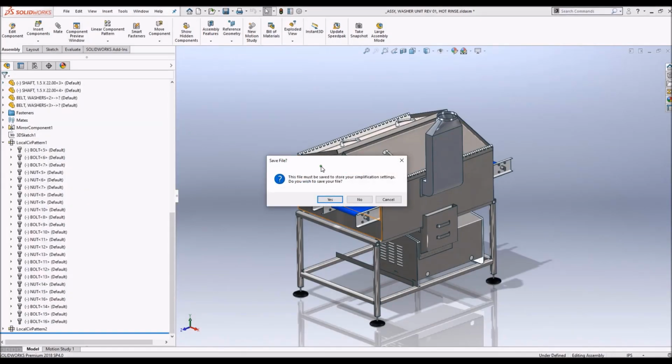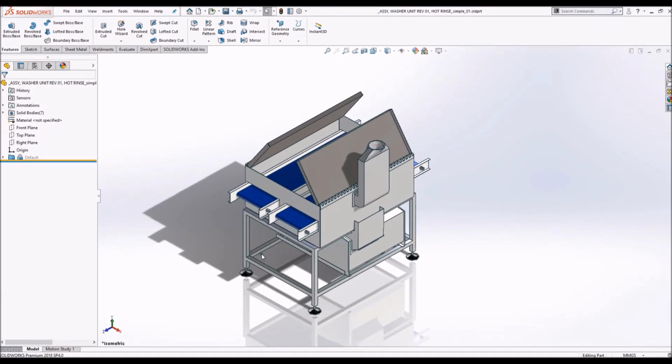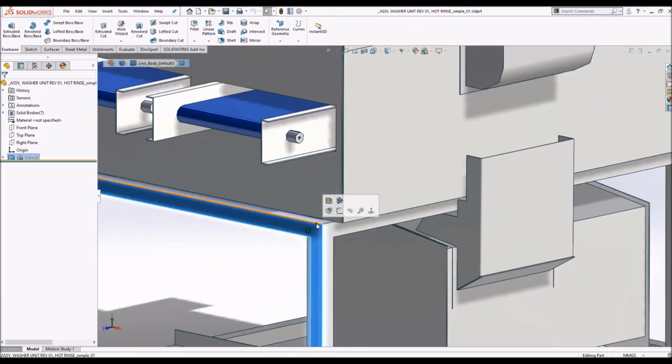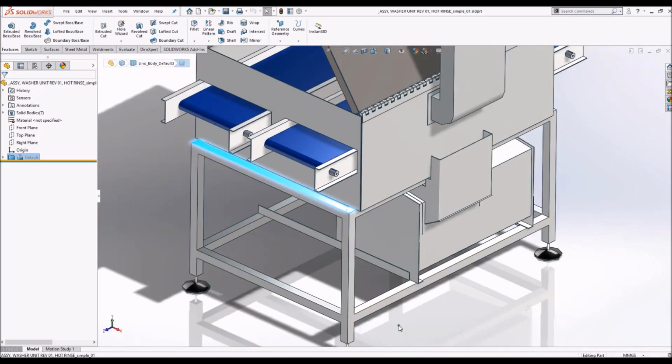When all settings are done, the simplification process can start. We save all settings in the Solidworks model. This allows us to exchange and reload models later. We will now jump to the result. As you can see in the simplified model, the solids have been joined.